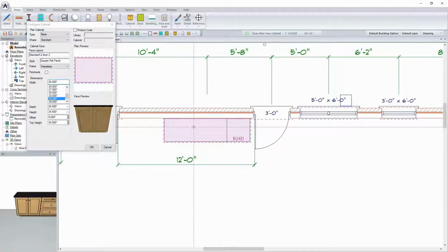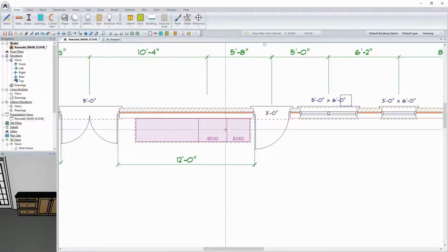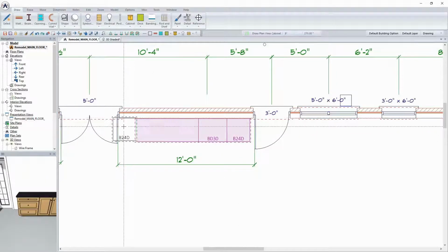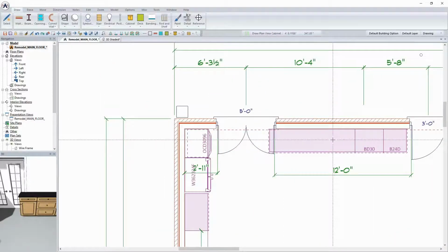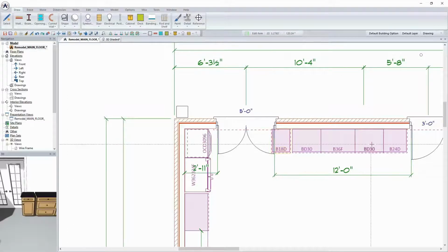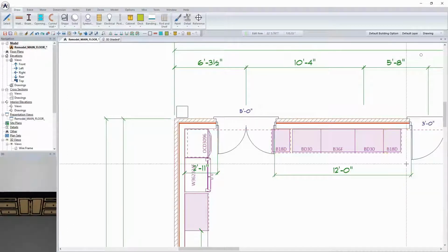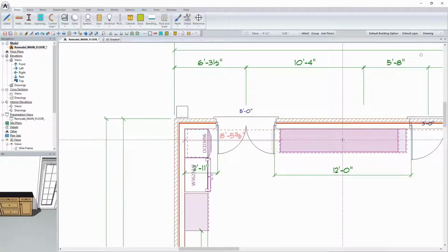Okay, and using Control E, I can pick the drawer, select now, add the same drawer panel here, pick the drawer, select, and add the 24-inch vanity in there, and that's beginning to set up exactly what I want as far as the sizing is concerned. And it's clear this is not going to work if that door is set, so what I can do is edit on the fly cabinets to fit. I'm picking 18 inches, and I'm going to repeat edit that over there, and then run a cleanup. And now, for design purposes, I'm just moving that in between.